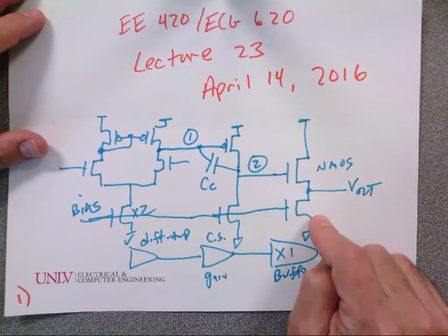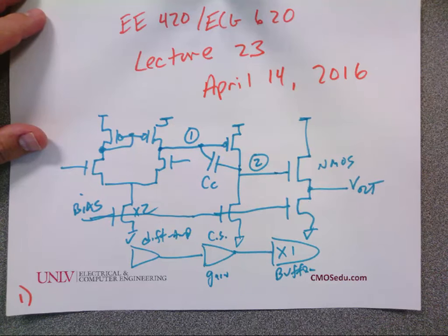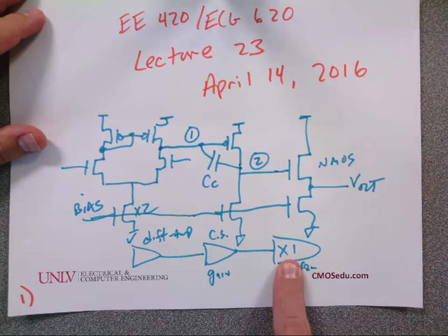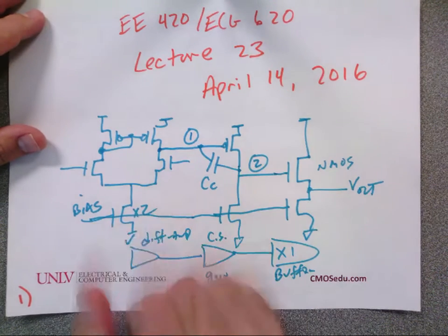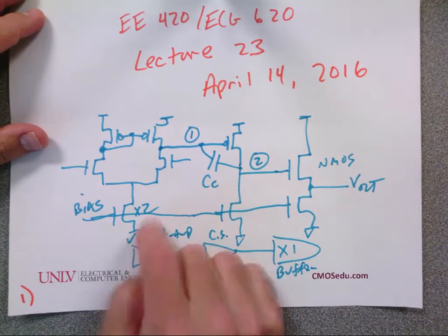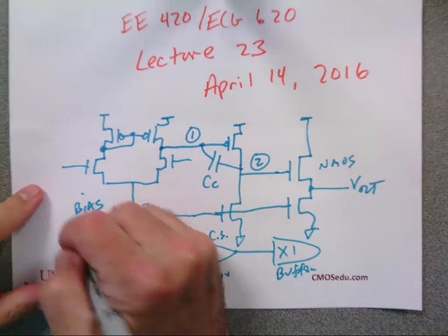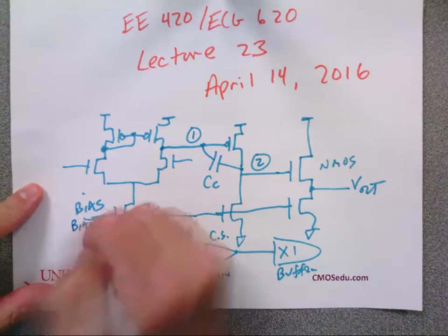All right, any questions? Yes? Just for clarity, that's 2x2, you mean another NMOS in parallel? This one? No, this means 2 in parallel, twice the width, m equal 2. So I could draw it as 2 separate ones, or I could draw it as m equal 2. So bias 4 goes to connect to that, and bias 3 connects to the other. No, bias 4, if I'm using, connects to all of them.